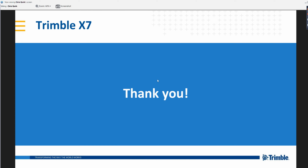One more question. Can you georeference your point cloud in Cloud Engine? Yes, you can. You can register that to some survey points as well. So you can do your plane-to-plane registration, and then you can tie that into coordinate points as well. Absolutely.